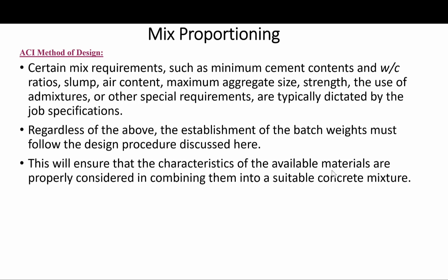As was stated earlier, the job specification may dictate certain mix requirements, such as the minimum cement contents and water cement ratios, slump, air content, maximum aggregate size, strength, the use of admixtures, or any other special requirements.